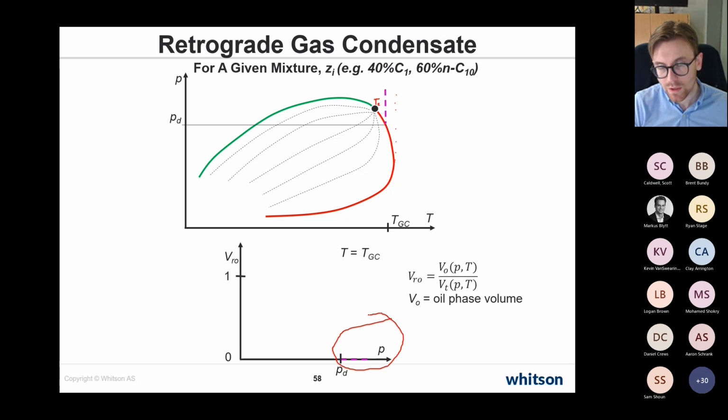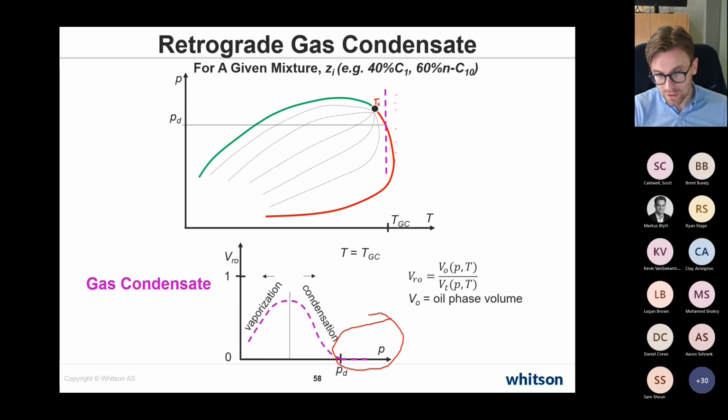So when we plot the liquid relative volumes, there's no liquids, and as we go below the saturation pressure, liquid is coming out of solution, and the liquid relative volume drops. Then it flips and turns non-monotonic, and to explain this, we need to know our K values. You'll have a condensation-driven period and a vaporization-driven period. This is what you'll see for the first time now, and later we'll use it to explain why the RV curve looks like it does.